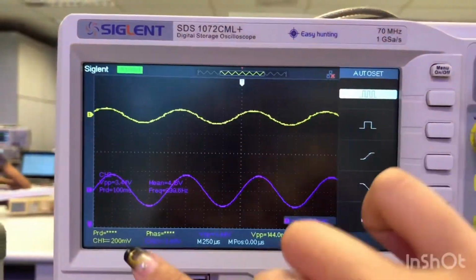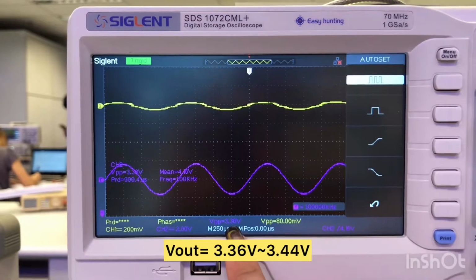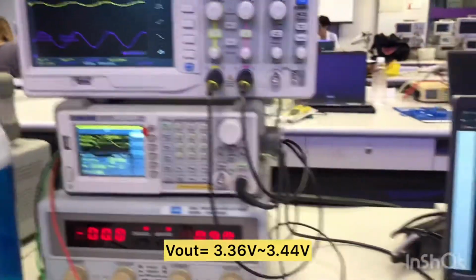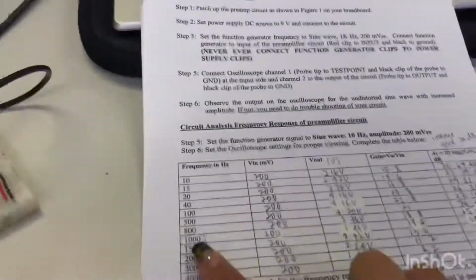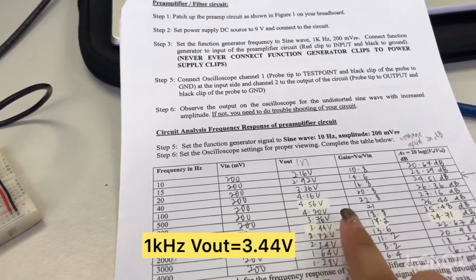As you can see, when the input frequency is 1 kHz, 200 mV peak to peak, the output voltage is around 3.36 volt to 3.44 volt, which is very similar to my lab results of 3.44 volt.